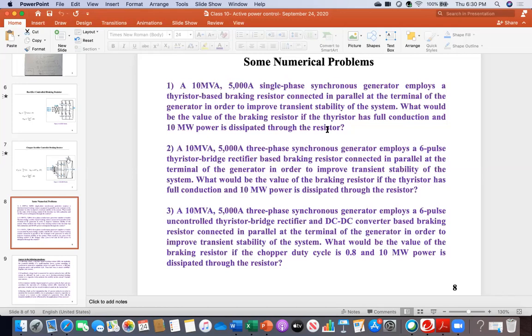No. So everybody, that is the mistake. See, this is the three-phase synchronous generator. That's why your answer differs: like number one is single phase, but number two is three phase. Yes, Dr. Ali, I went wrong there. That's why I got a VDC completely different from both of you. So let's check, this is three phase. So probably you have the wrong Vm value.